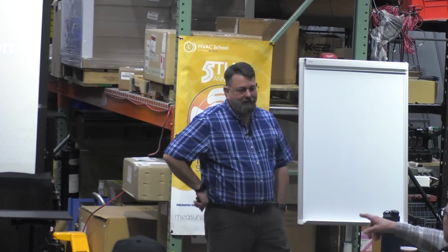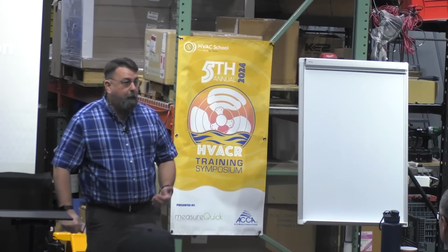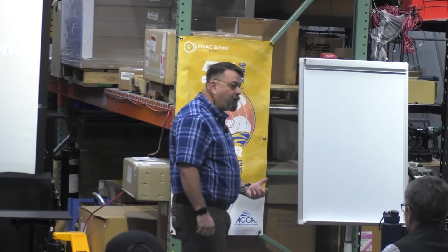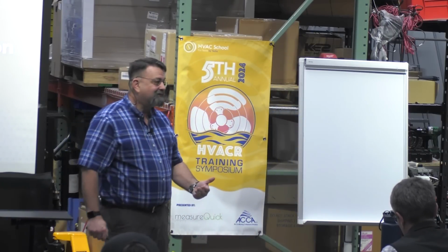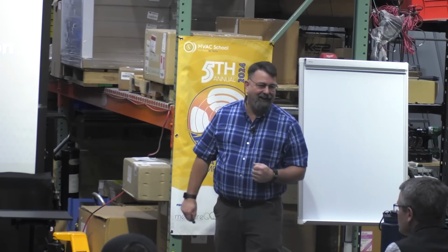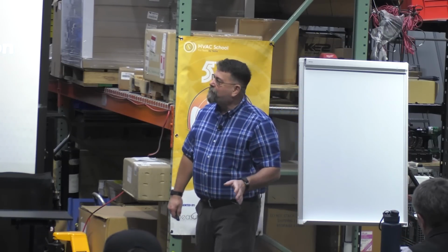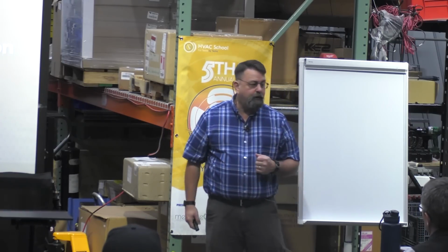Yeah. No, go ahead. I saw a blue valve in that picture. Is that some kind of shut off to the TXV or something? Yeah, exactly. So it's very common to have a hand valve to turn off the liquid inside a refrigerated case because somebody's got to clean this thing, right? You guys saw it, that one wasn't all that pretty inside, right? Well, they get a lot worse. So somebody has got to shut off the refrigeration, open up that coil, take a hose to it, right?